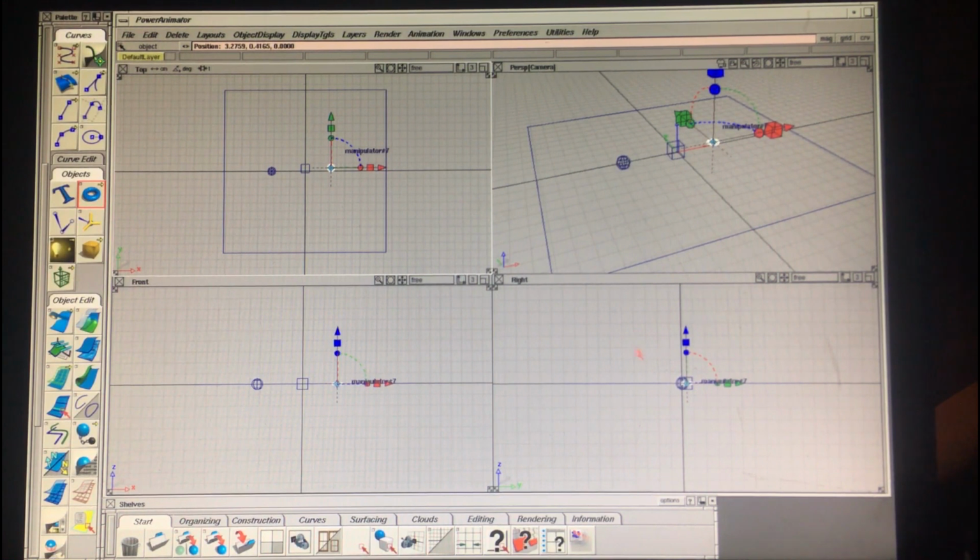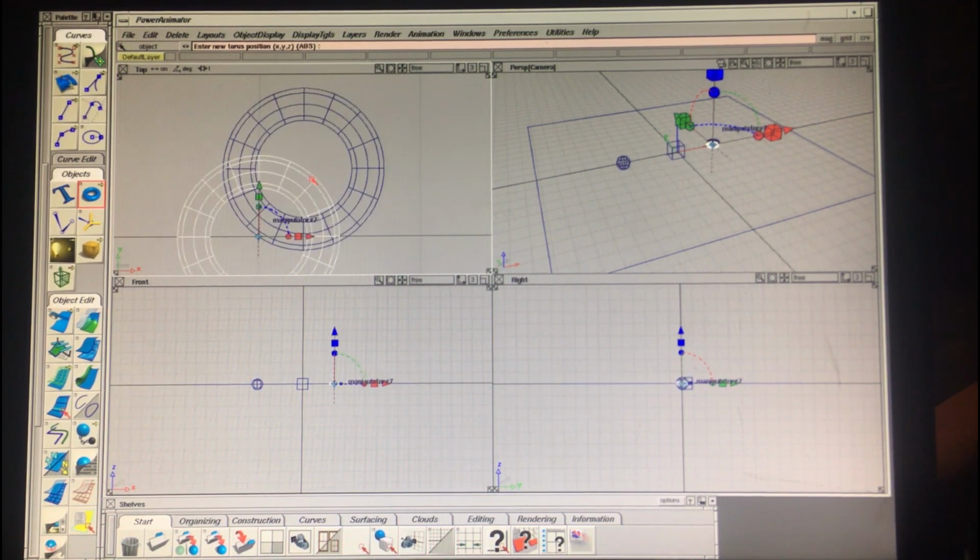Oh yeah, we want to move these things up on the floor. So here's another trick that's kind of like the focus in my. If you hold the Alt and press L and click in the scene, you'll see that it focuses in on it. Oops, didn't mean to do that. I clicked the torus without deselecting. So Control Shift left, pick nothing.